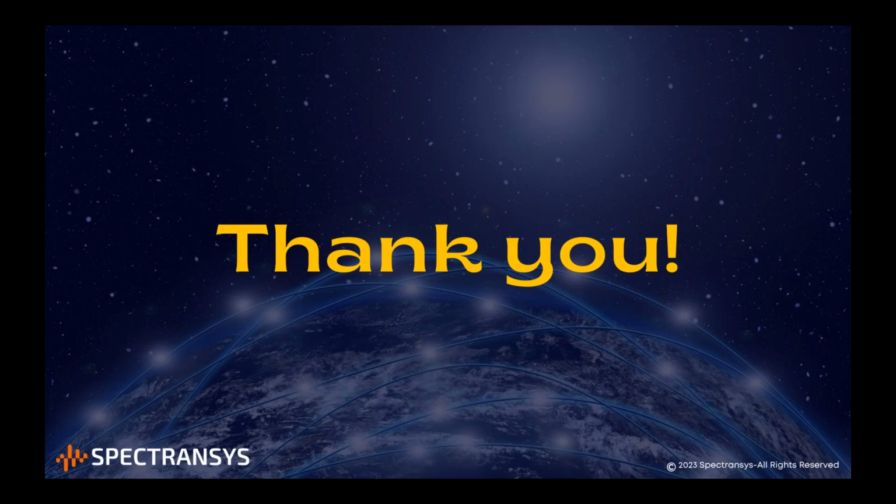Normally ISO is for casings, and of course ISO is also there for the shaft vibrations. Especially, I think ISO 20816 part 2 or something is for gas turbines, and part 3 is for steam turbines, I think. So they try to give you all that. So the standards are basically up to you.